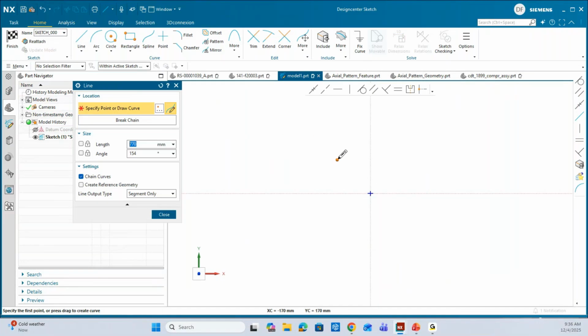So notice that my cursor is a pencil. I've got that little sphere. Go over here to line, and it's going to want to snap to it, and it's going to change to yellow. If I'm over a point, there's my little green, so I'm going to go ahead and select on that. And now I'm previewing that curve I'm creating. I've got the dimension displaying with it.